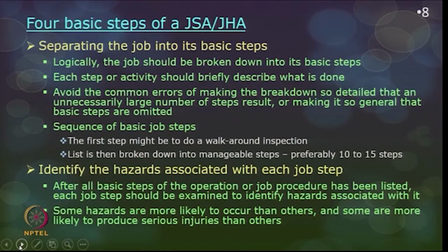You may have to separate the job, identify one operation, loading and unloading of reinforcement. You will have to break down the job into a number of basic steps. Logically, a job should be broken down into basic steps. Only if you break down the steps, you will know where the hazardous steps lie. So, each step or activity should be briefly described: what has to be done.